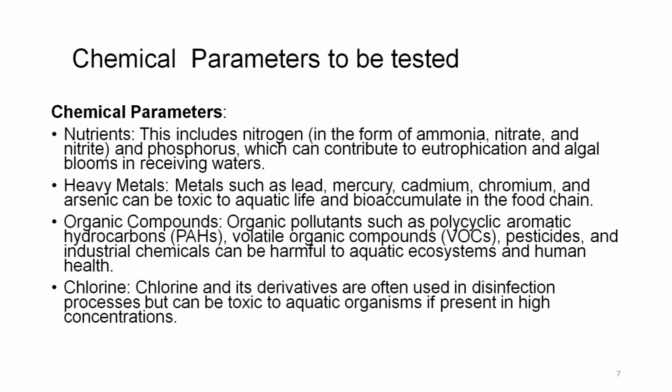Chlorine. Chlorine and its derivatives are often used in disinfection processes, but can be toxic to aquatic organisms if present in high concentration. And if you may recall, we had studied the chlorine dioxide oxidation method. There also we studied that this chlorine dioxide can be toxic to aquatic organisms if it is present in high quantities. So, all these need to be tested properly, so that they are no longer harmful to the aquatic ecosystem or to human health.